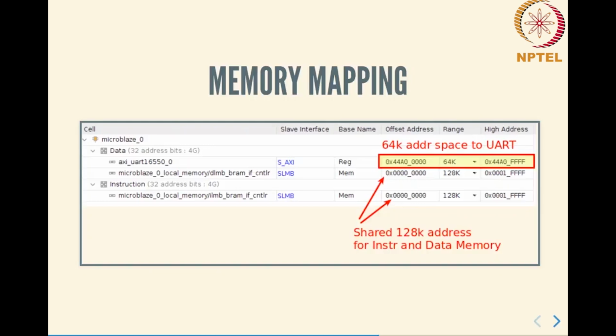This idea of memory mapping is something that is going to be very important in terms of actually building and using systems in future. So although you don't need to worry about how to allocate address spaces and so on, the core idea of memory mapping is going to be used in order to both map peripherals into your AXI address space as well as communicate with them using programs that are going to run on the MicroBlaze.